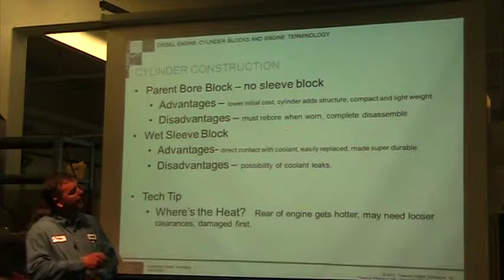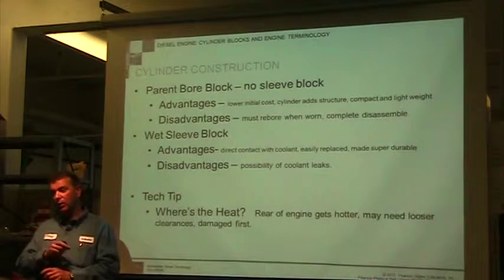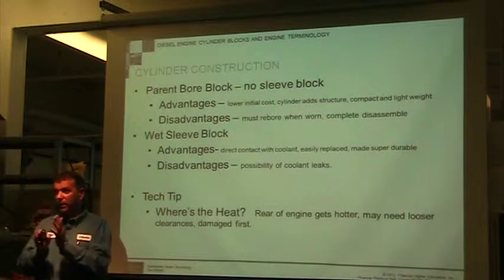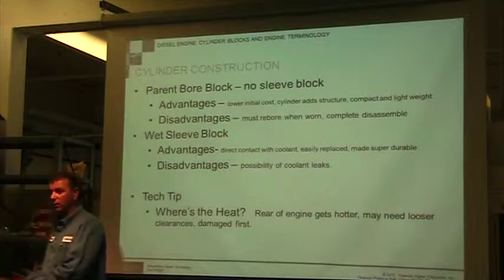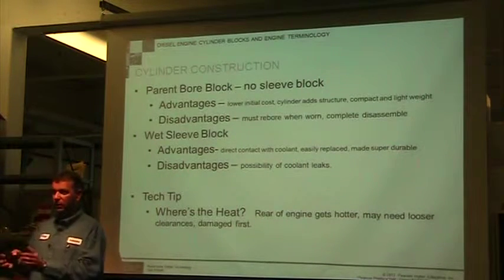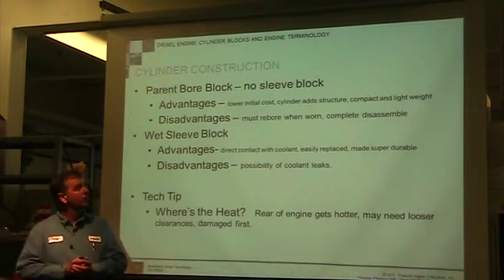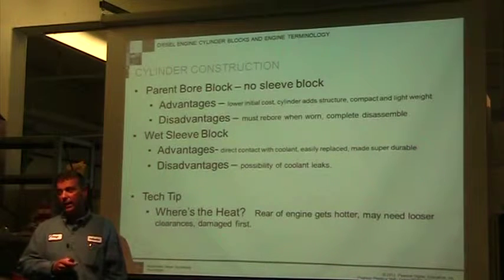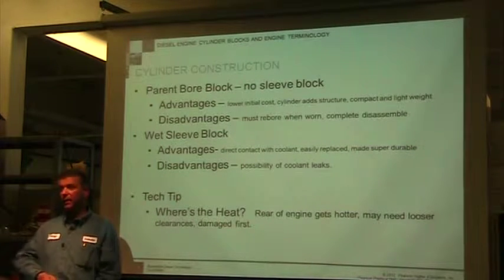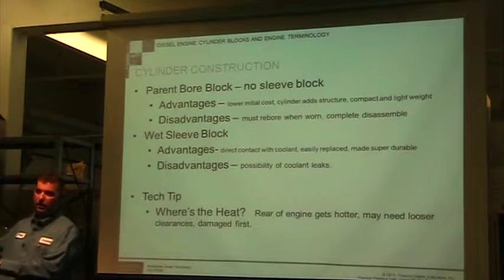If we can make the engine cheaper by using a parent block and making it more rigid, and we can make it more emissions friendly, then the cost of just replacing the engine versus rebuilding it is going to be a better option. And so you'll see more manufacturers look at it and say, as a technician you cannot get everything back up to 100%, so we're going to make it to where you cannot rebuild our engines.